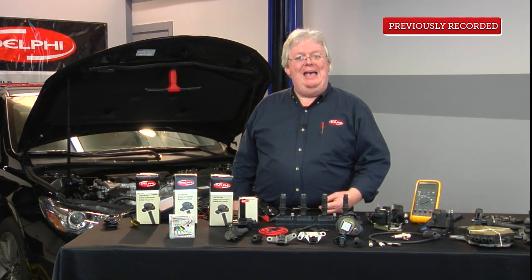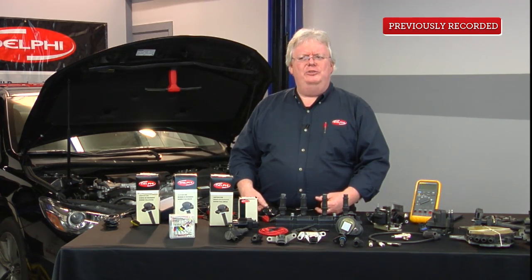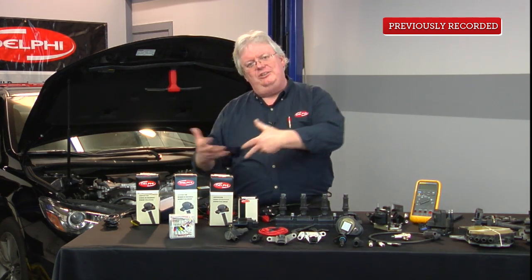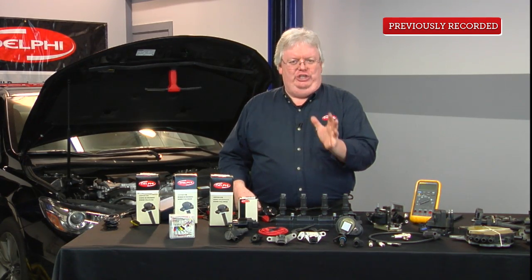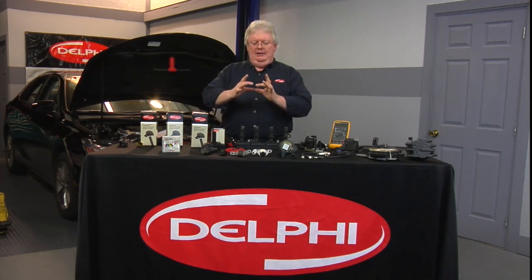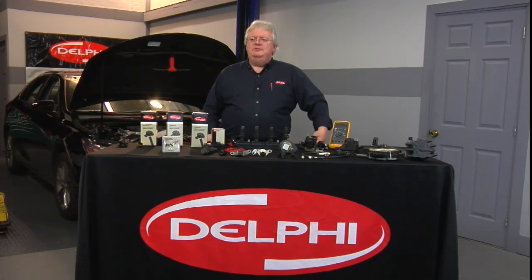I know iATN, I think, has an actual Pico forum just for those users. And other scopes are the same way. I've used the OTC 2-channel, little job you can fit in your pocket, USB connection to your laptop. Pretty nice little scope. Really, any scope is a good scope if you start using it. And if it's pretty crude, simple, 2-channel, even the 1-channel little job that looks like a cell phone you can stick in your pocket, that's a good place to start. But whatever you got, get good at it. If you want to upgrade it, that's great. But yeah, it's a good comment on storing patterns.